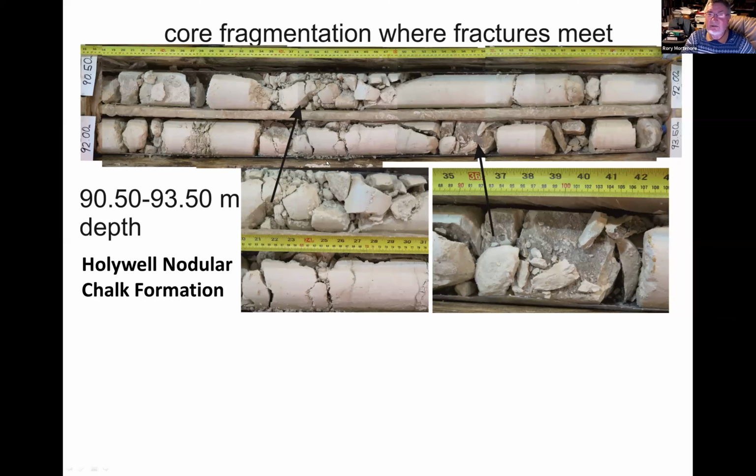So most of that would be closed, grade A, but it would probably be logged, by those who are not inexperienced or don't have the confidence to do otherwise, as a grade C, open fractures all the way through. And that has a huge impact on design and depth of putting piles in some areas. So this is again a good case of needing to have a workshop to reach an agreement on what you think those grades are.